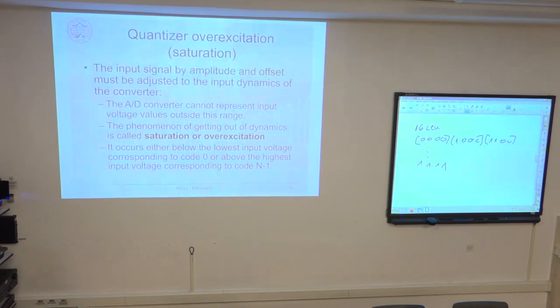For actual AD converters, you also have the problem of the reference voltage, because the absolute accuracy of measurement is based on the absolute accuracy of the reference voltage that you supply to one pin of this AD converter, because it only gives the ratio to this reference voltage. So, for example, if the value is whatever maximum value, it is an integer ratio to this value that you have supplied to one input pin. And if you want to have a given absolute accuracy, you must have very high stability of this reference voltage that is insensitive to the temperature, to the changes in the power supply voltage, so it must be stable.